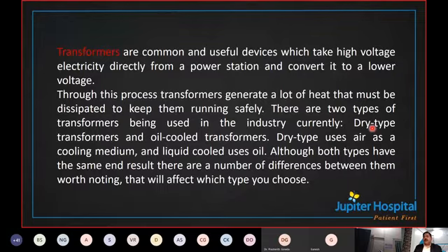Now, if you see there, because dry type is always, there is an advantage that you can fit it inside the campus. Because what happens if you do not have a huge plot and your building size is just enough to take care of the 9-meter periphery outside the building where the fire tender has to move, then you cannot put any of these services on the outside.